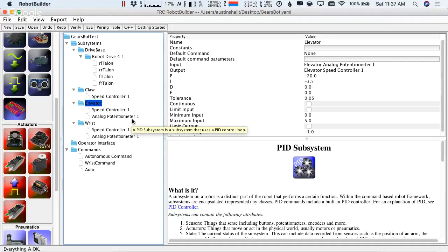So we have time or some other method and PID control. Why did you use PID? Because I have sensors on the mechanisms. So you want to use PID because it's really annoying for your drivers to have to sit there and be like, okay, it's at the right height right now. Oh, my finger slipped and now we're no longer at the right height. It's much easier to just have a button that says, go to the bottom position, and PID will take care of it. That's why you use it, because you wanted to go to a specific position. Yep. And the position is called the set point.